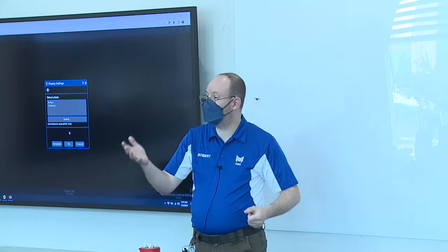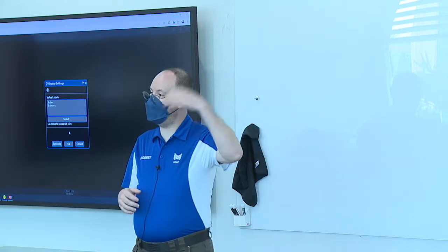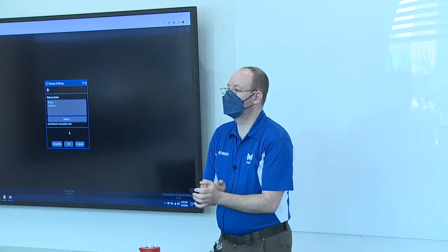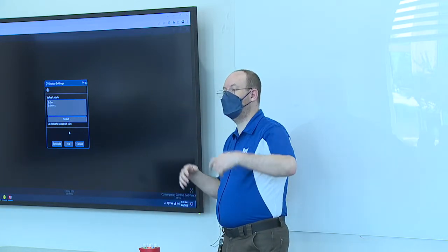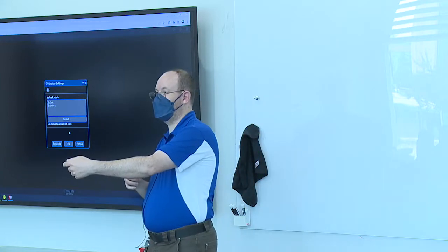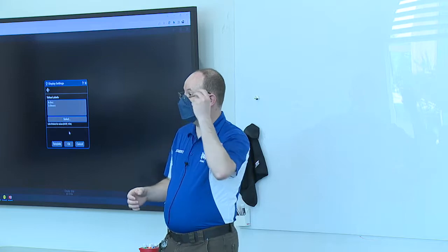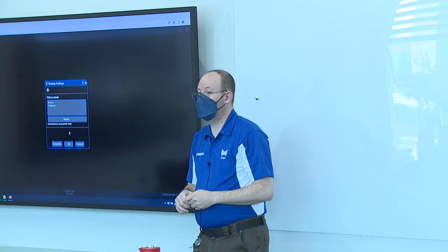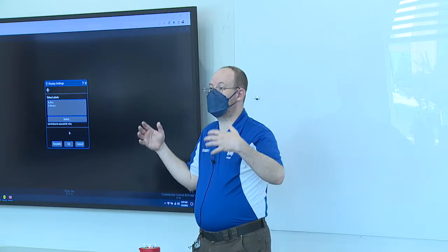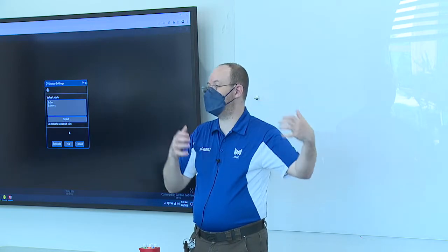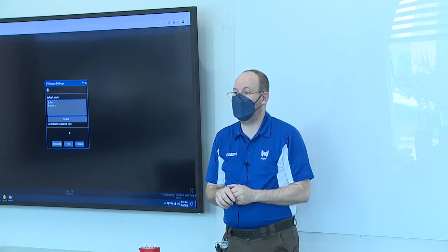Depends on the time of year. Fair enough. In winter, do you turn the boiler on or do you turn the boiler off? You actively choose to disable it. So if your control system dies in the middle of winter, that boiler is going to turn on by default. It is defaulting to a safe state. That's something we have to think about with controls all the time.